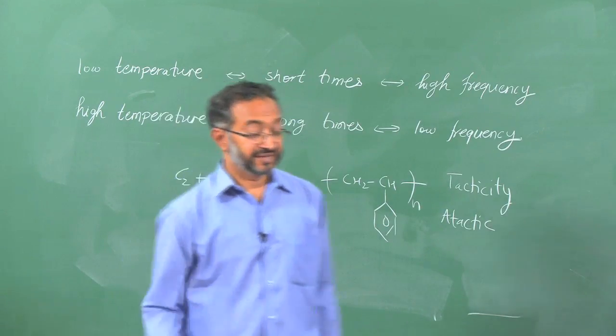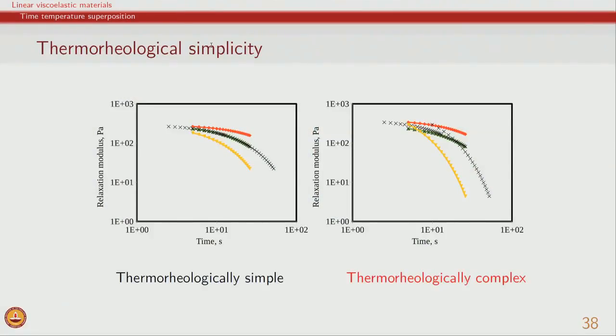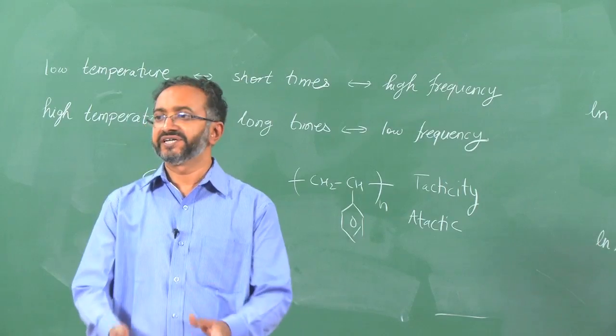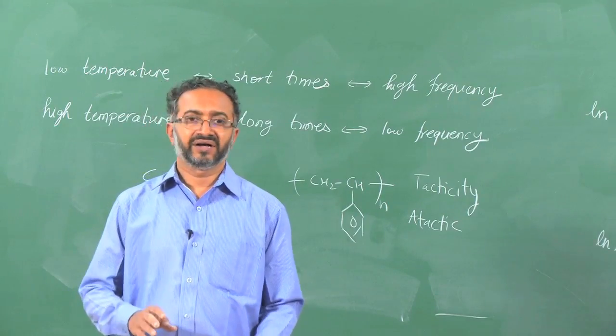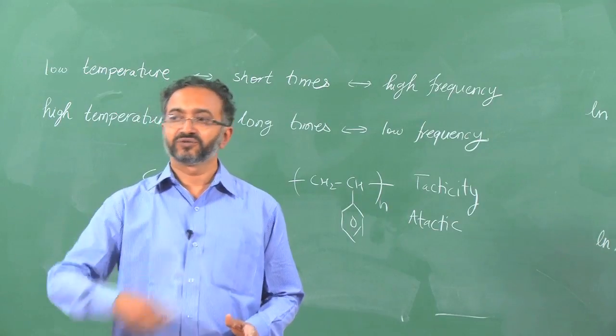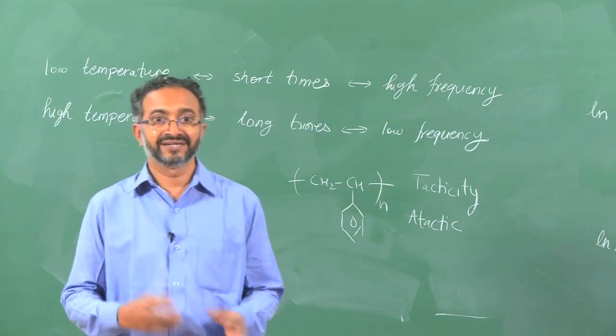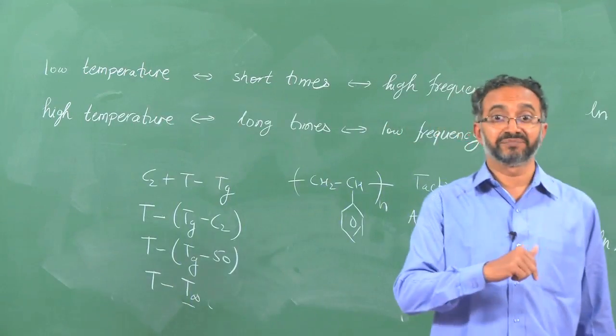So, what will happen is, he is pointing to another possibility. Let us say if PET itself, right, if I am testing it, let us say my processing temperature is 250 degrees Celsius. I want to understand behavior, but again I do not want to do too much long term testing. I will just take the material to 300 degrees Celsius and test it, but at 300 degrees Celsius maybe some oxidation and a few other things may happen.